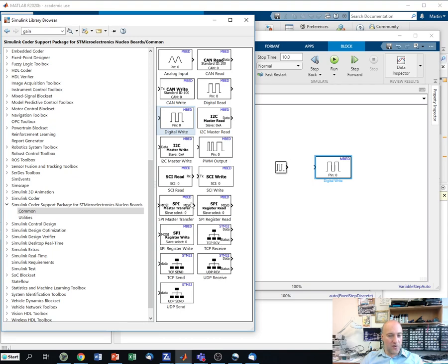If you compare SPI and I2C, I2C is a 2-wire bus, bidirectional, but the SPI is at least a 3-wire bus, where you have one wire from the device to your host and another wire from your host to the device, plus some clocking signal.